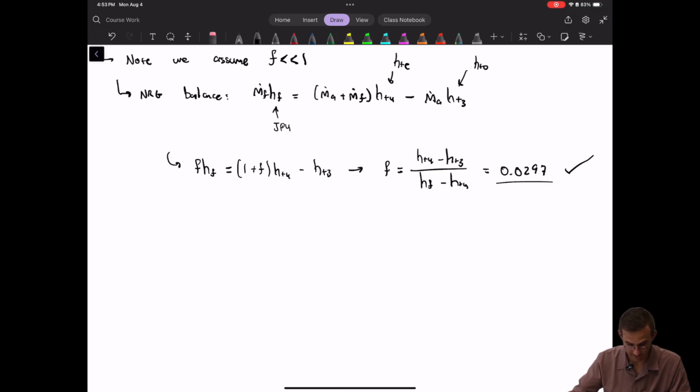Let's go ahead and calculate the efficiency numbers. So the overall efficiency of the ideal ramjet is, using the non-dimensionalized form of the equation, we already have f, tau f. We know what tau f is. That's just hf over cp t naught. We defined that earlier in this lecture. And then we have our non-dimensionalized thrust.